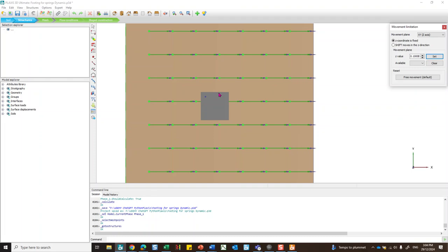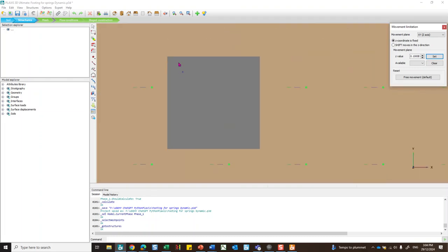In this, I created just a polygon. I specified points here, the distance between the points, say 1 meter, okay? And the first pair would be half a meter from the edge. So I have several points here, node next to stress point, node next to stress point, so that the area served around each pair would be 1 meter square.